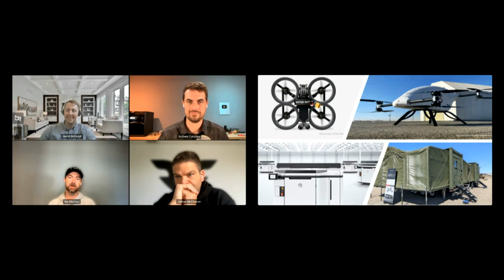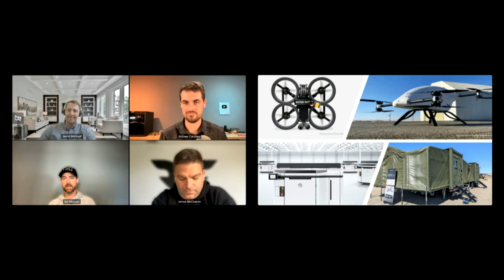Obviously, we have printers now, but sometimes it's a de-risking factor to go there, because you're working with an industrial grade machine with a lot of in situ processing and analytics to tell you what could be going wrong. Whereas if you start with FDM and do even small batches of parts, things go wrong. One build to the next is going to be pretty wildly different.